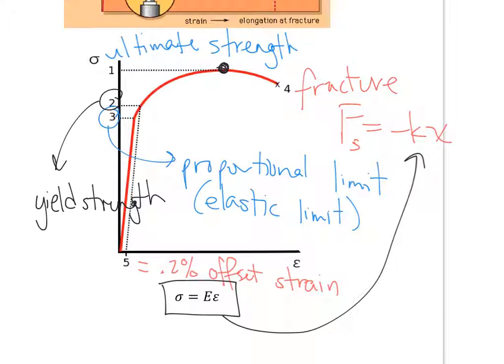So look, notice here, this from here to here was originally probably like this. All this range is already getting stretched here in the middle. Look, you've hit the yield stress a while ago, and now it's taking even less stress to continue to stretch it more. It's reducing actually. There it goes. See it? Fracture point, separated.